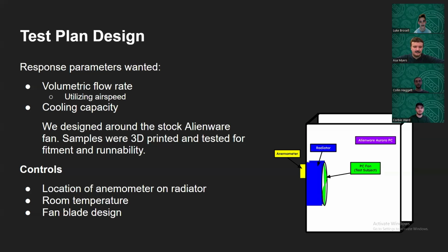After the components were taken out of the fan, we were able to take the measurements and model the fan in SOLIDWORKS. The fans were designed by modeling a single blade and using SOLIDWORKS' circular pattern function, so each blade is equidistant from each other for each blade count.